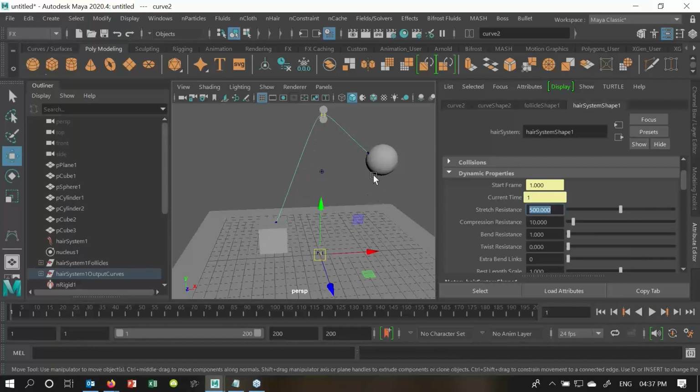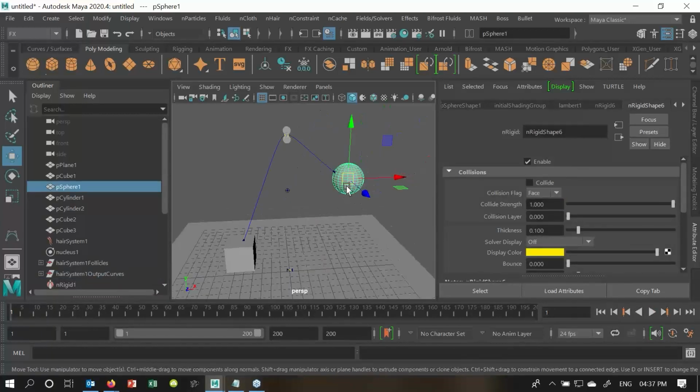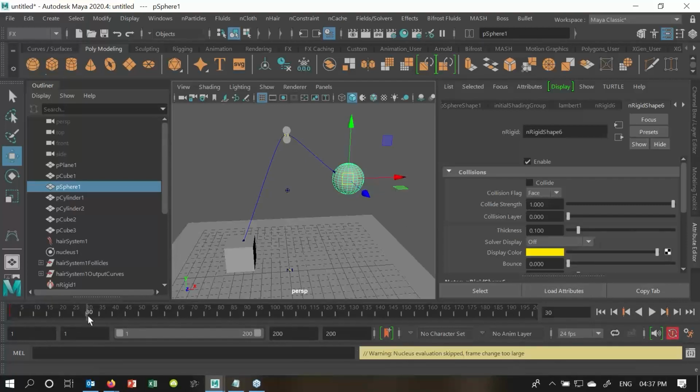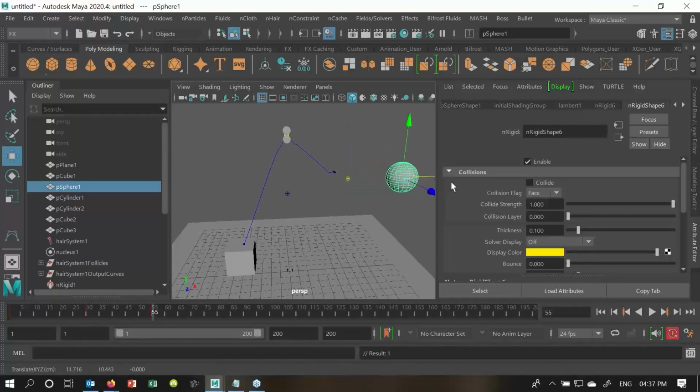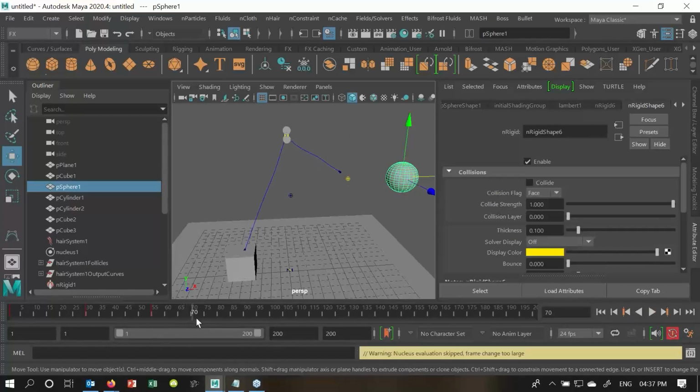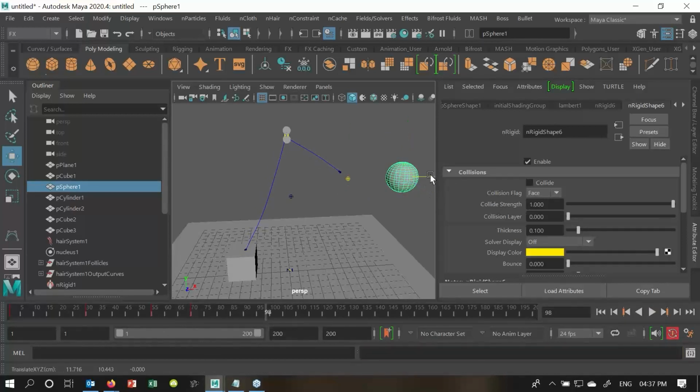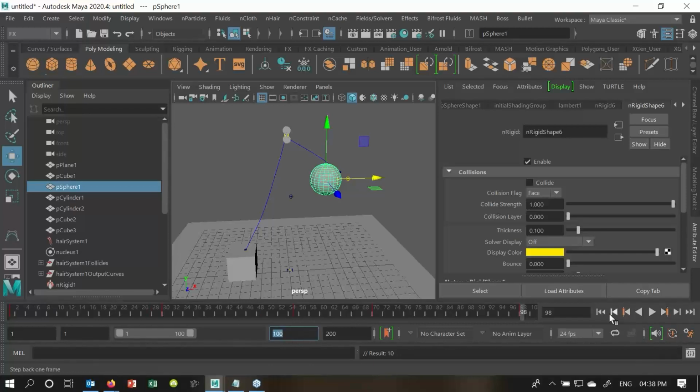Now I'll add animation to this object. If I move this object, then automatically this has to come up. So select, set key. This is already animated. At my frame 30, set key, between 30 to 35 this starts to pull over here. Set key till 70. Then after 70, it will again come over here, set key. So my total duration is 100. I'll stop my auto key and start and play over here. See this? This has come out very fast.